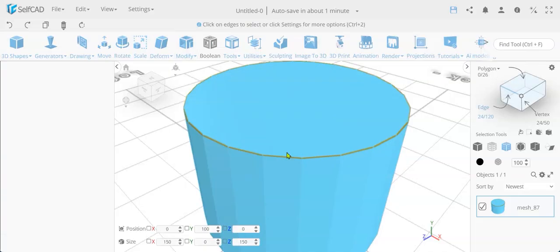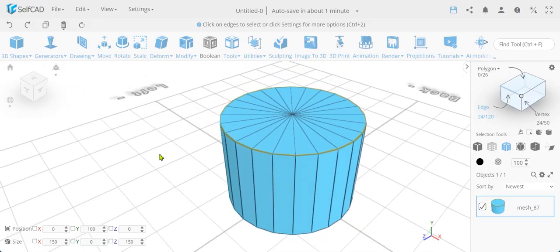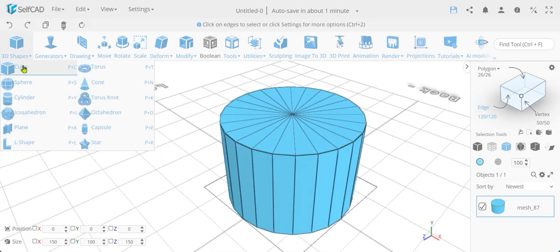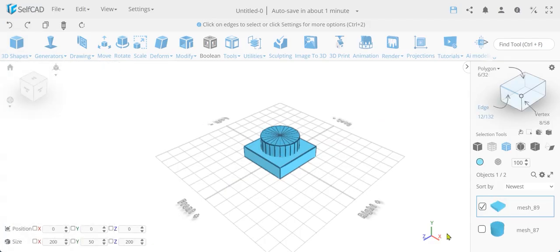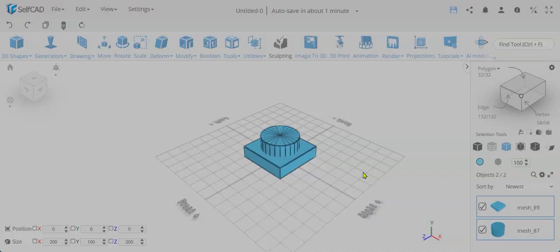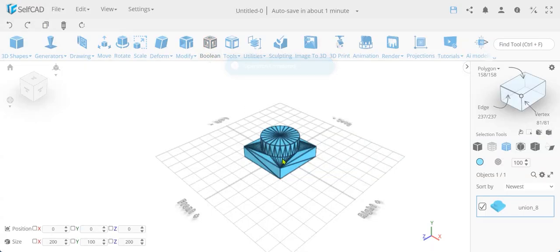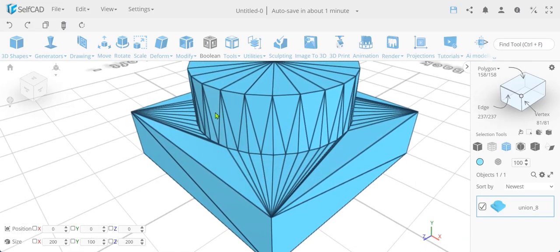Now let's look at an example where solid mode makes a significant difference. We'll create another primitive. Leave both the width and height at their default values. Next, merge the 2 objects using Ctrl+U, which performs a Boolean union. Notice what happened to the topology. The Boolean operation rebuilt the mesh, replacing the clean quad layout with a mixture of triangles and irregular polygons.